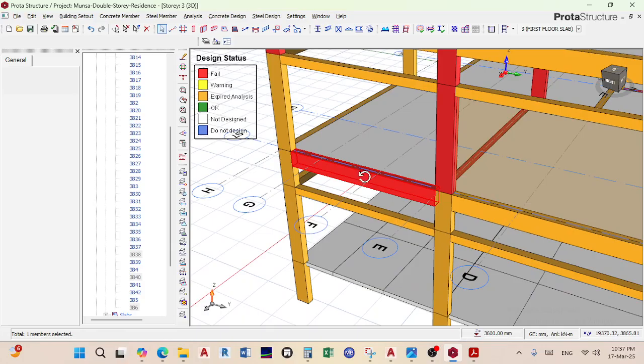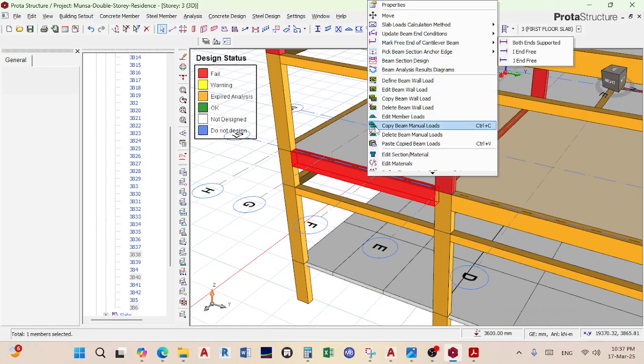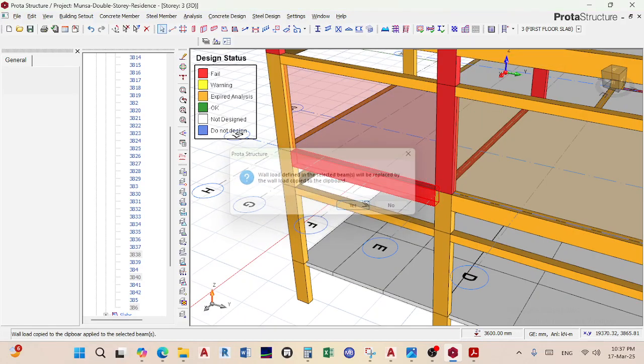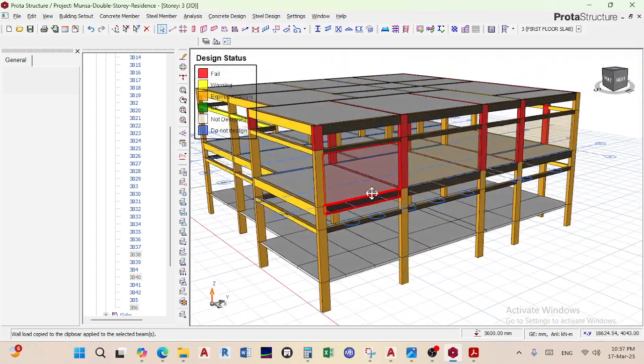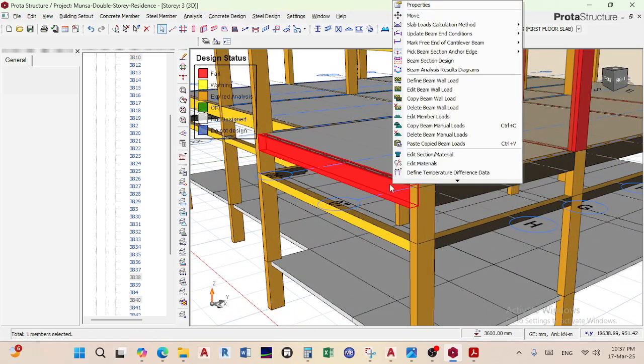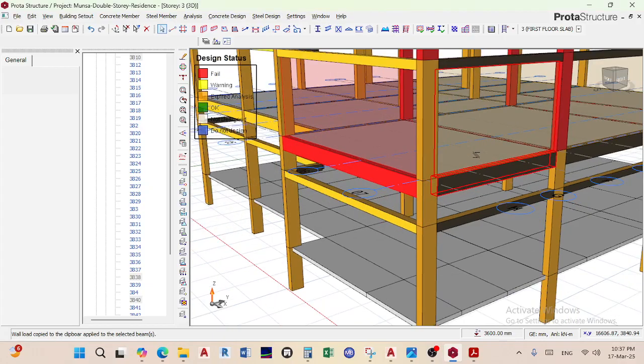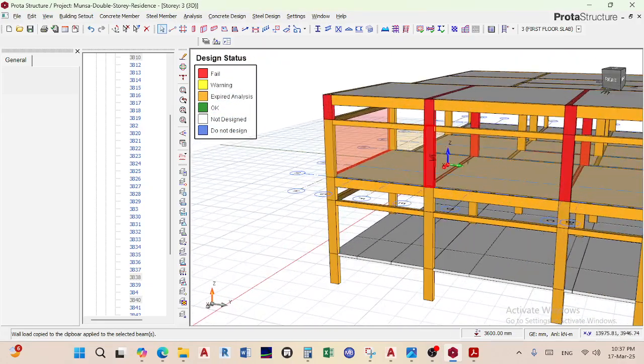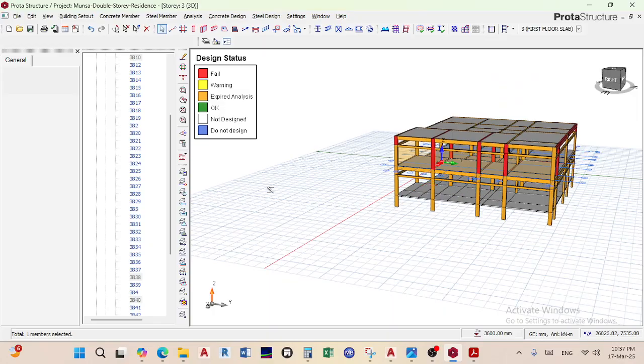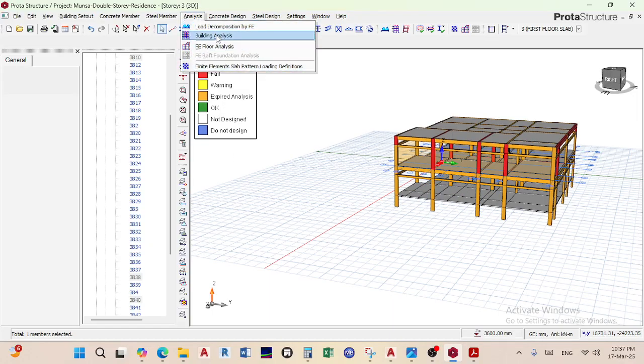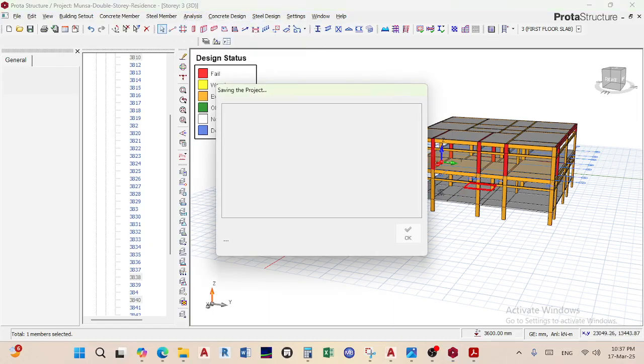And then you can do the same for these other ones. You click, you select and paste, you click until you go around, you load them, especially the external ones, because they're the ones that are going to be solid, to have solid filled blocks like that. And then if you like, you can decide to rerun the analysis after having loaded with the 200 bricks.